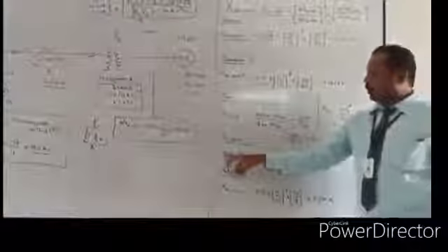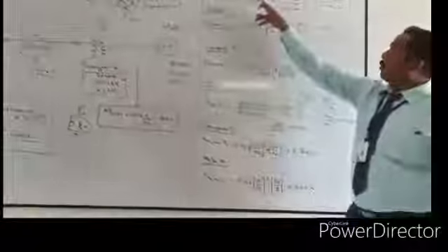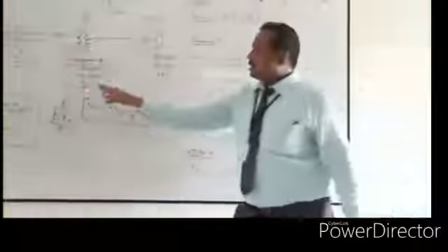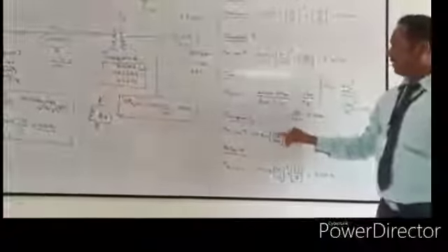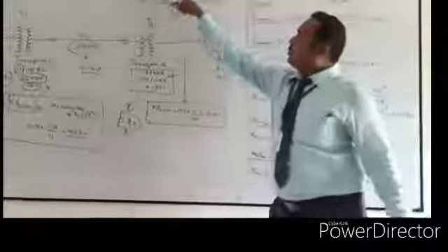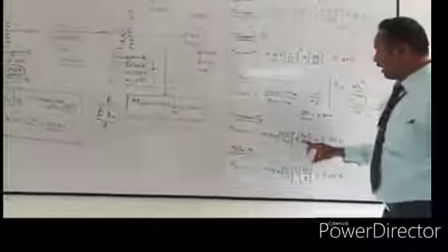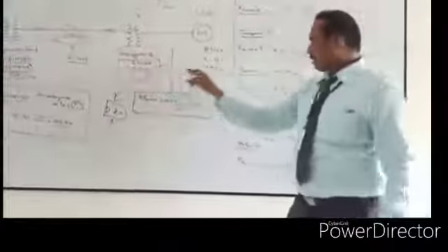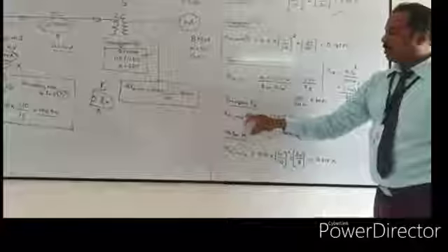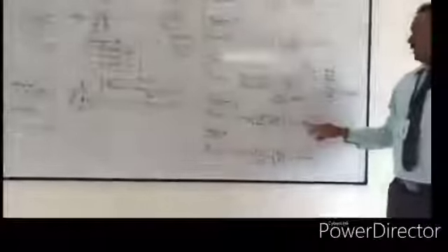Again we come to this formula for the transformer T2. So the new per unit value of the reactance of the transformer T2 is equal to the old value multiplied by kVp old by kVp new, squared, and MVAB new by MVAB old. So the kVp old is what is represented on the transformer side, 110 kV. 110 is the kVp old. What is the new kVp? This is what we have just calculated, 100 kV. This is presented here, and 30 is the common value. MVAB new is 30 MVA, and the rating of the transformer T2 is equal to 20 MVA. This is going to act as the MVAB old. So finally, what is the per unit value of transformer T2? The new per unit value of the transformer T2 is equal to 0.363.